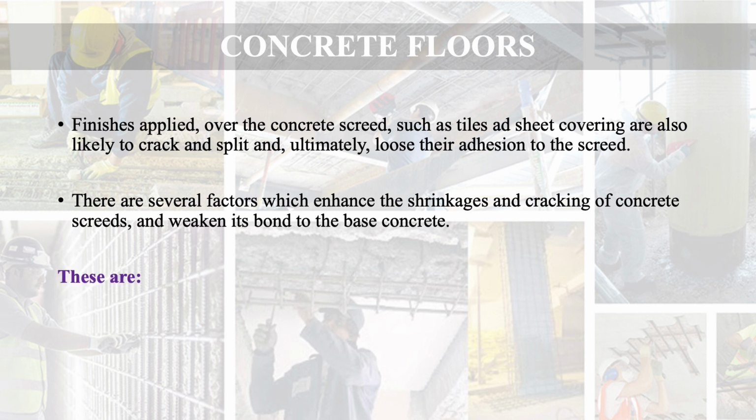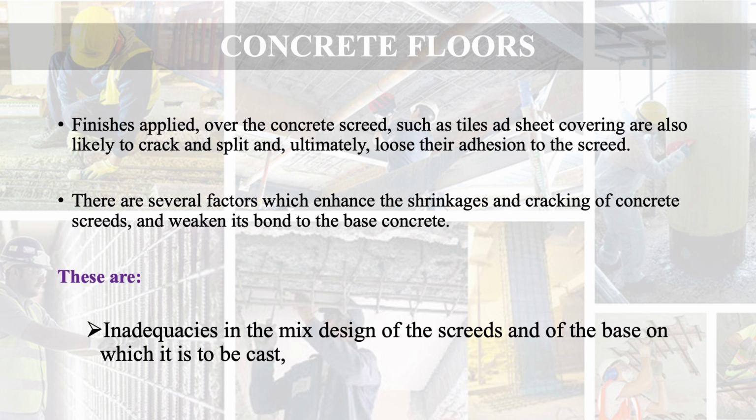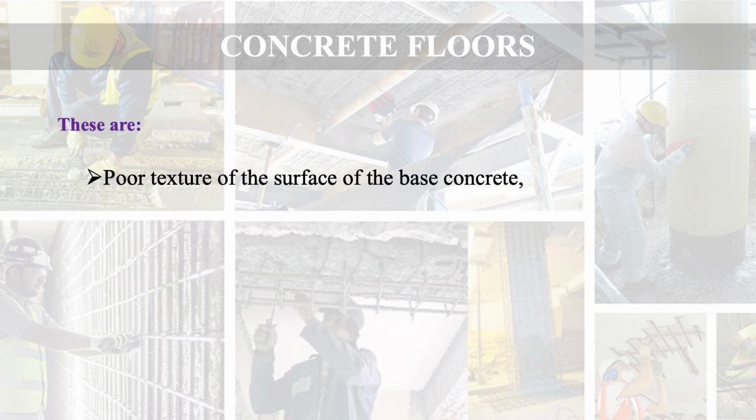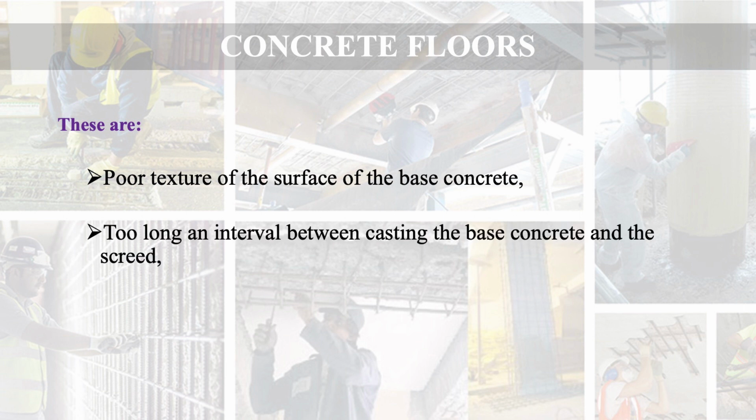These factors are: first, inadequacies in the mix design of screeds and of the base on which it is to be cast; second, poor texture of the surface of the base concrete; third, too long an interval between casting the base concrete and the screed. Means that the gap should not be too long.